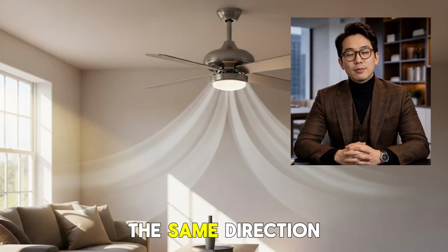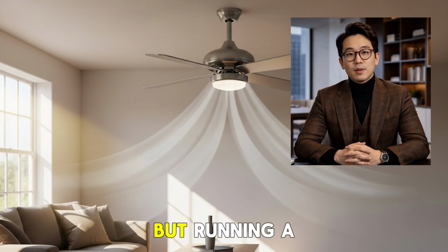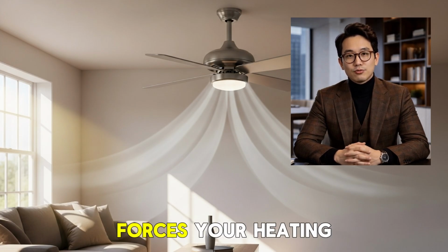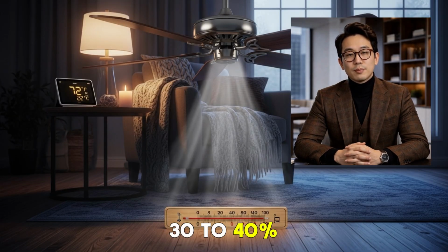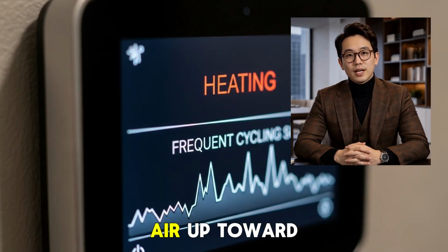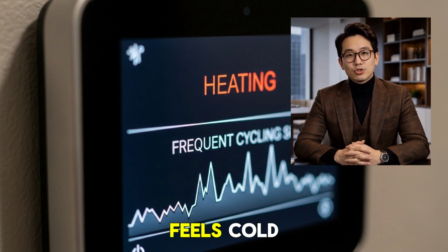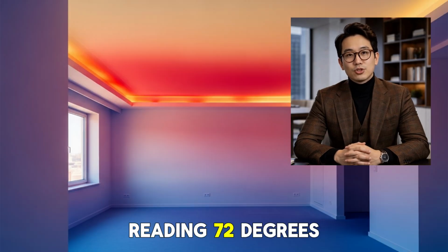The fan spins the same direction year-round, pushing air downward in summer and winter identically. But running a fan in the wrong direction during winter forces your heating system to work 30 to 40% harder to maintain comfortable temperatures. Your furnace cycles constantly, fighting against airflow patterns that push warm air up toward the ceiling and pull cold air down to floor level where you actually live. The result is a room that feels cold despite the thermostat reading 72 degrees.